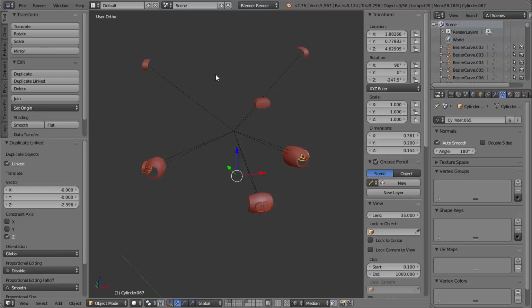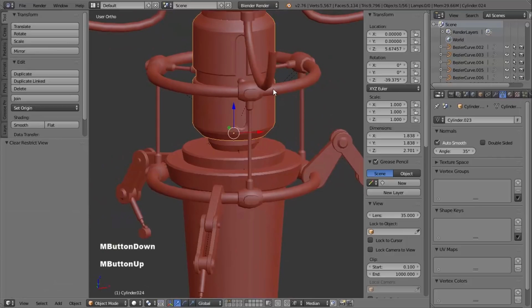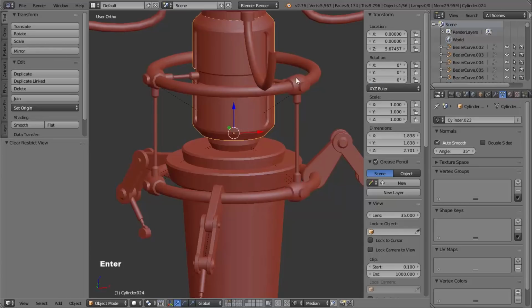So bringing everything back again, I'm going to press Alt and H and I can select my main trunk object, and from before we've got this rotation value set. So to rotate everything back to the proper place, I can just click in that field and zero that value, and it's taken all of the light fixtures with that rotation.